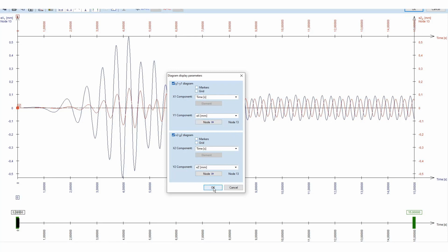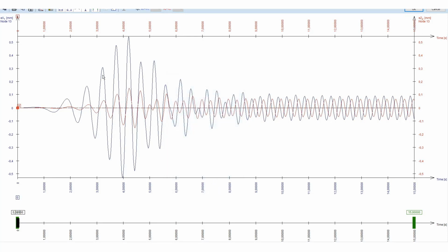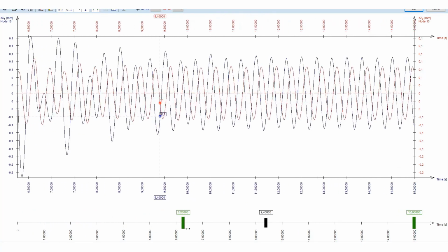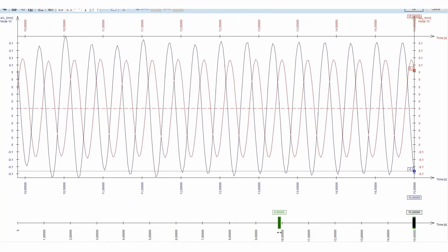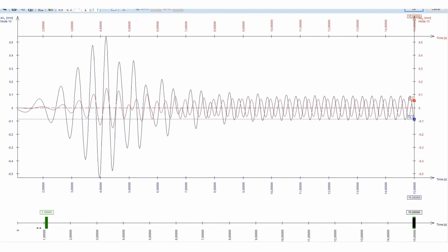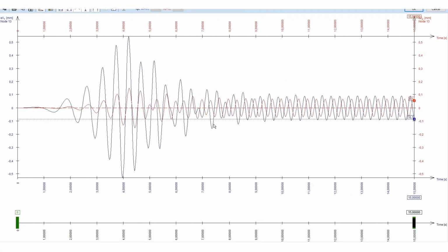The results clearly show that we have relatively high amplitude vibration as we accelerate the machine. After that, the free vibration is decreasing due to the structural damping. At the end, we get a pure and stable forced vibration solution, where the responses are controlled by the external excitation. If we narrow down the plot range, we can have a better overview of the steady-state solution. We can easily get the results for the accelerations as well.